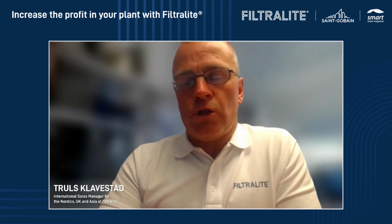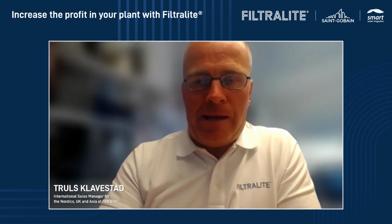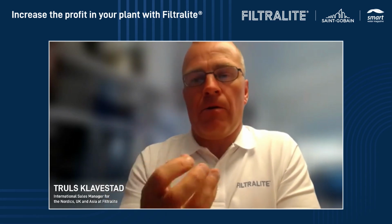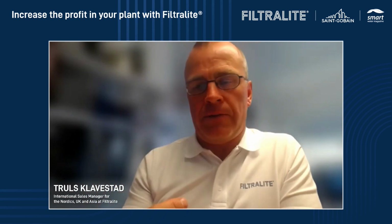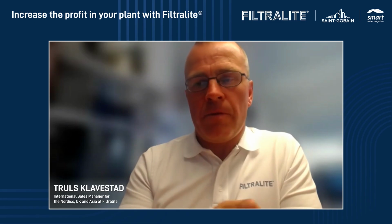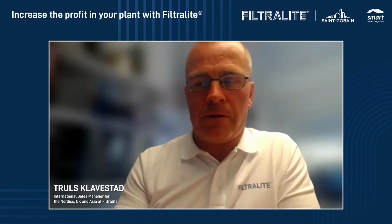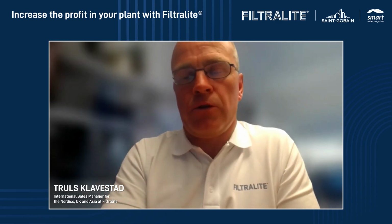Their case was that they should never regenerate the material anyway, because they were just looking for a carrier of the biofilm. So in these cases, you don't need to take out the activated carbon and regenerate it. But as I said, in the beginning activated carbon outperformed Filtralite, but in the long term, Filtralite was a much better solution.